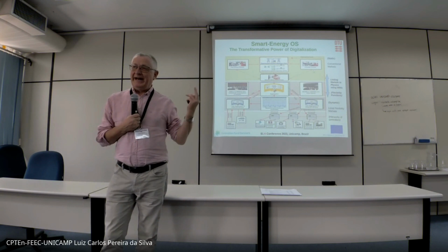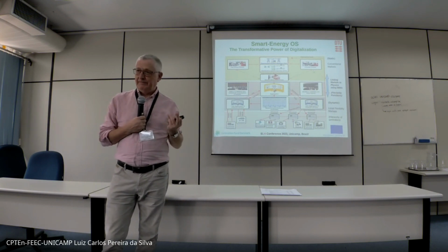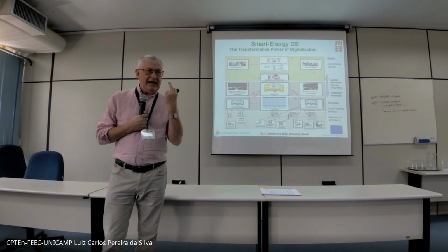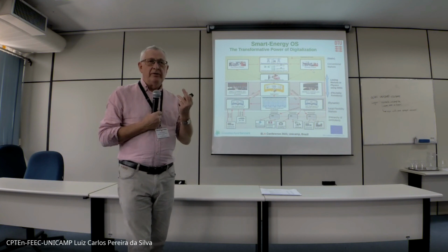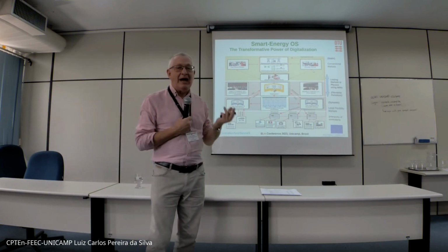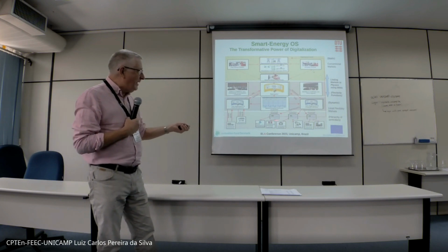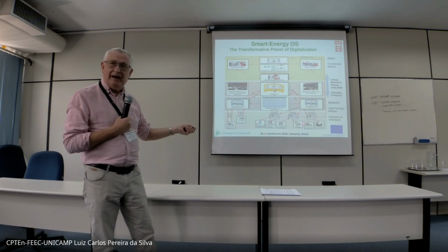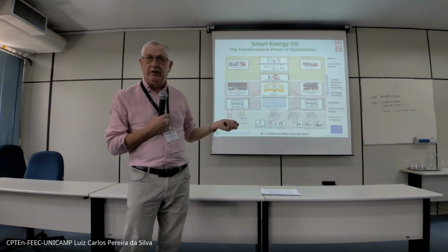We have put that into what we call the smart energy operating system. That's a framework of models arranged in spatial temporal hierarchies, which on the lower level describes the dynamics of the wastewater treatment plants or the buildings and so on by these simplified models, gray box models or data-driven digital twins.